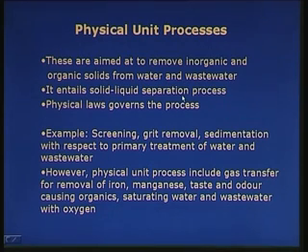that is sedimentation. We use gravity sedimentation for the solid liquid separation process, and since it is a gravitational process, the physical laws govern the process. So, we can use physical laws, that is classical mechanics, for design of systems to remove the solids from the liquid. Like sedimentation tank and so on and so forth.